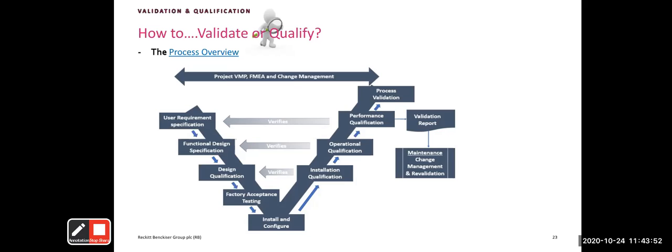So for the operational qualification, you want to be sure that you did not have any hitches during your installation qualification. So if there are deviations, if there are challenges you had during your installation qualification, you want to be sure that those deviations have been justified, and you've already had CAPAs to close out those deviations before you move on to the operational qualification. Where you have unjustified CAPAs, you cannot move on to operational qualification. But once that is done, you now start. That is the preliminary step of your operational qualification, confirming that there are no gaps during your IQ.